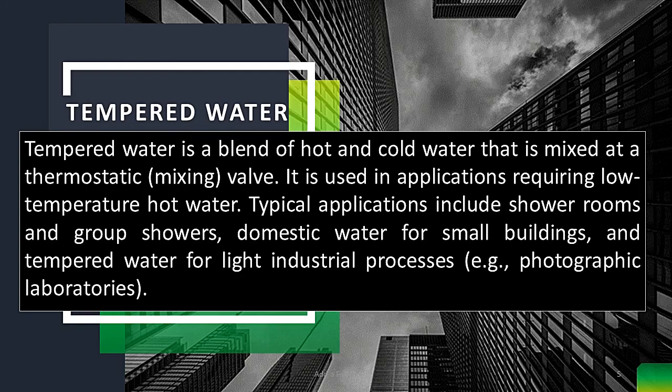Tempered water is used in applications requiring low temperature hot water. The typical application of tempered water includes shower rooms, roof showers, domestic water for small buildings, and temporary water for light industrial processes, for example, the photographic laboratories.